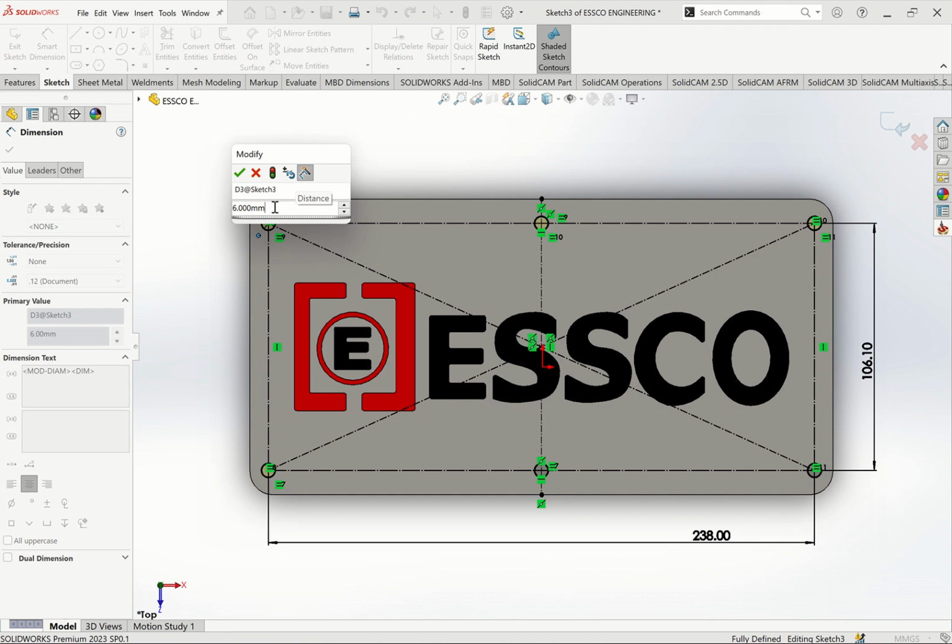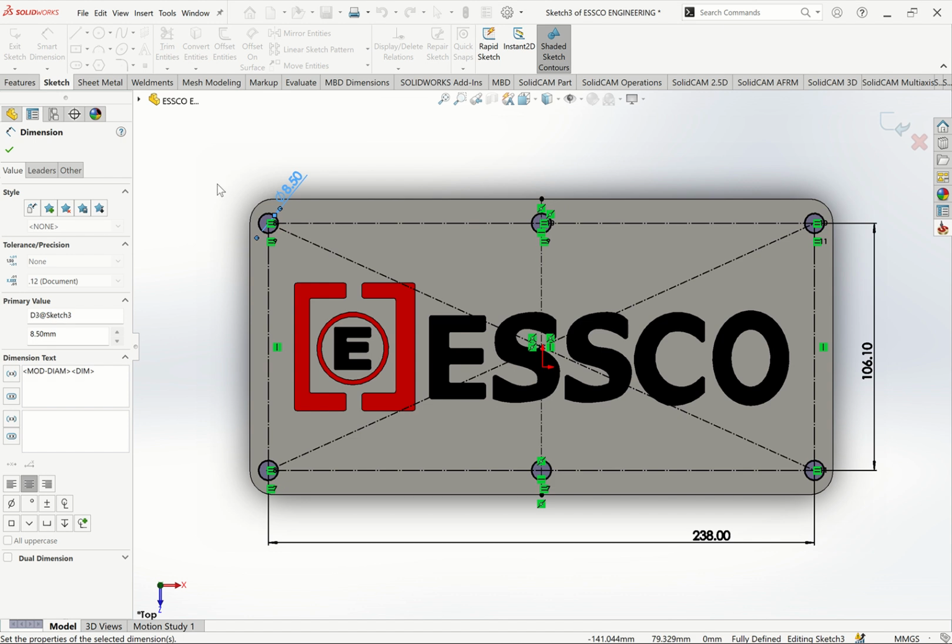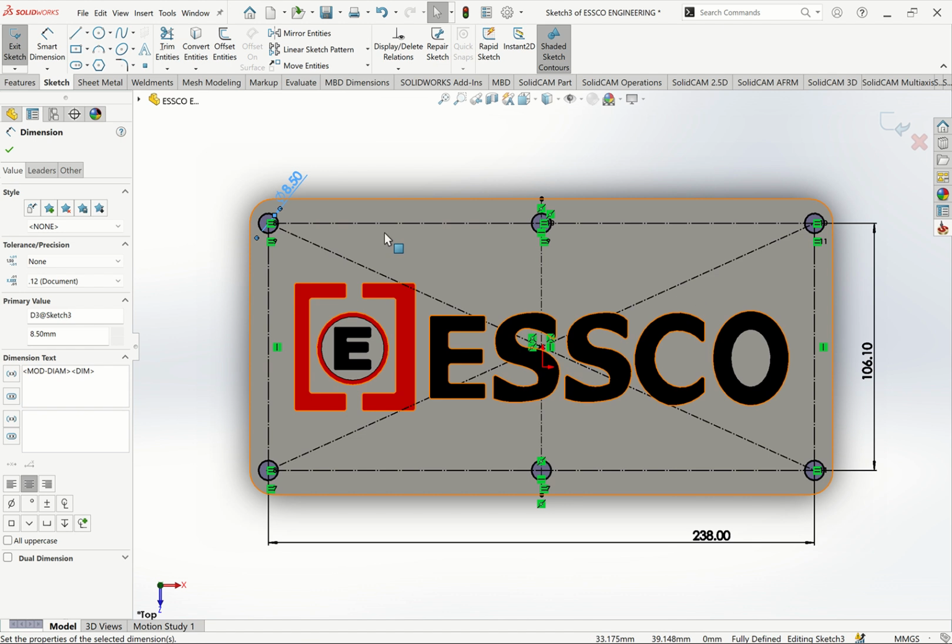I want to use M10 by 1.5, which means I will need to make my hole 10 minus 1.5. So this is the 10 major diameter, 10 minus the pitch, so I'll get the internal diameter. The internal diameter, ID, will be 8.5. So I need to make a hole of 8.5, then I do tapping and then thread milling.